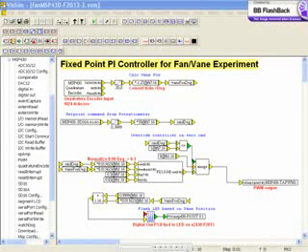When you start a new MSP430 project in VisSim, there are configuration setups to let VisSim know more about the part you are using. Some configurations are optional depending on the peripherals you will be using. The MSP430 config block is mandatory for each project and should be the first one configured. You can access the configuration blocks from the pull-down menu above or the browser window pane to the left. We have highlighted the configuration blocks and will pause the session so you can view them individually. Click on the highlighted config blocks or press the button to continue the session.